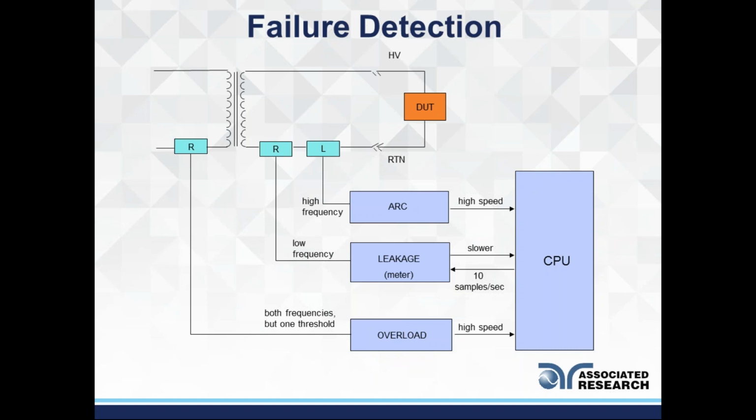If you are using arc detection in your Hipot testing, and the test resulted in an arcing failure or arc detection failure, that does not mean that the insulation of your product is in a very bad state or is breaking down. Arc detection will give manufacturers a good idea, or it may be looked at as a sign, that the insulation may not be in the best shape, and it may break down going forward or in the near future. So it's more of a quality check. So do not confuse arc detection with your breakdowns or high limit failures.